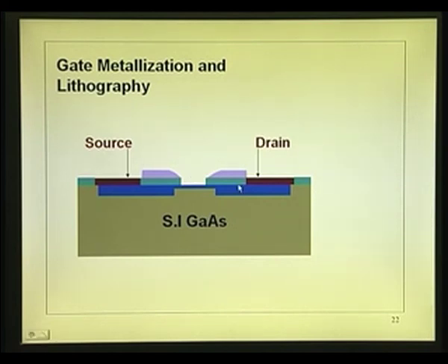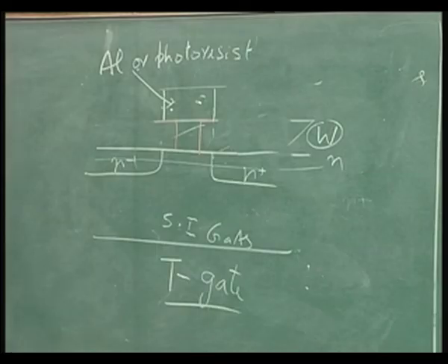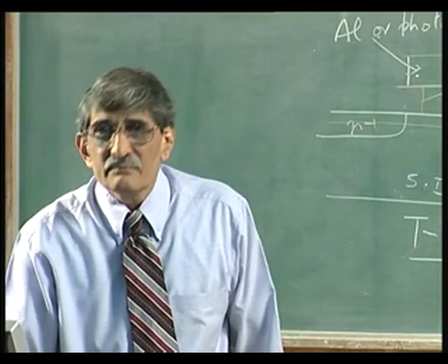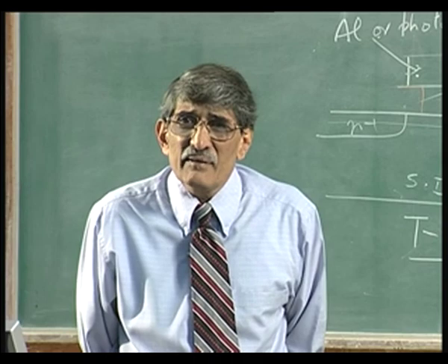In the sense, put photoresist everywhere, except this portion, I put it in acetone. The photoresist from everywhere with the metal will be lifted off, you will be left with this. So, the key thing here is after this step realize metal in that portion. Now, you can see you got the MOSFET which is self aligned with the distance between this gate and this portion realized by that T that you have got. Okay. So, this is the self aligned structure that you can get.